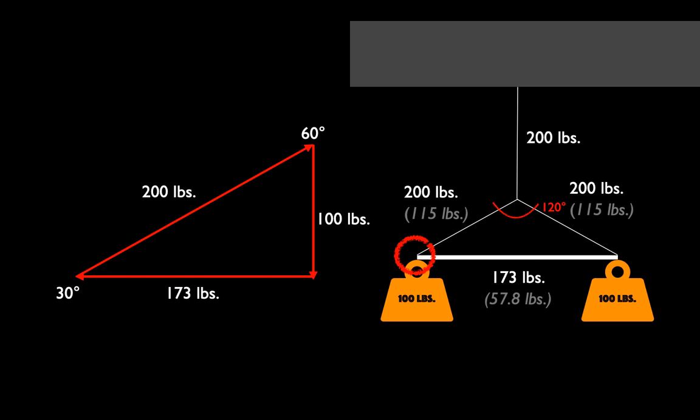They're going to have to almost double the size of the cables, and they're going to have to almost triple the size of the strut to handle these internal stresses if we want to carry the same load, right? There may be architectural reasons that this shape is necessary, but the structure is going to have to work a lot harder to successfully reach internal equilibrium in this arrangement than it would have in the previous one.